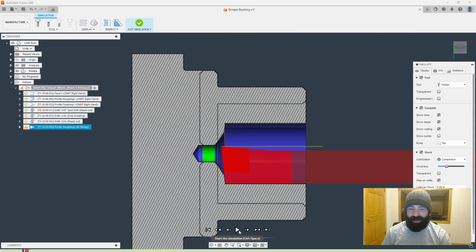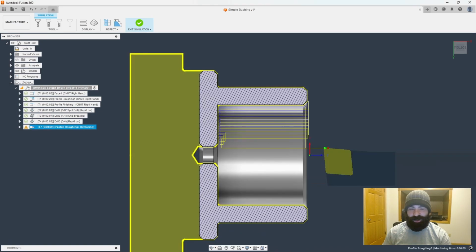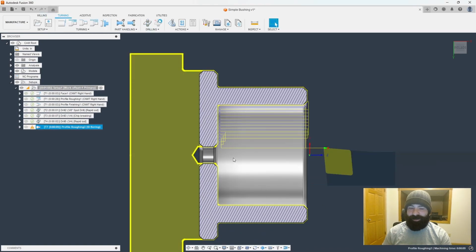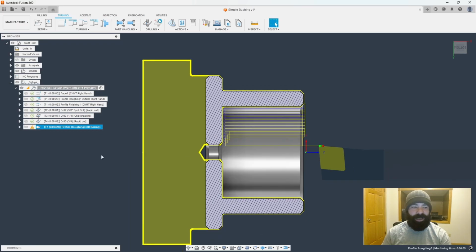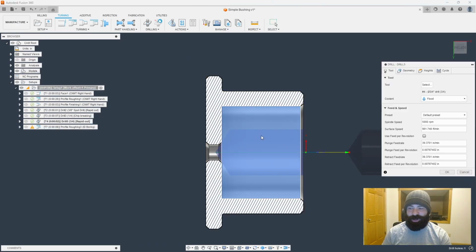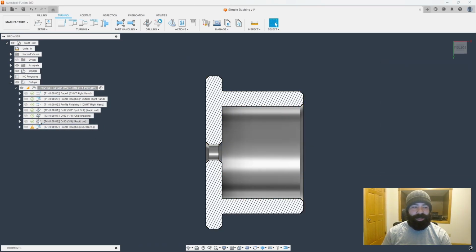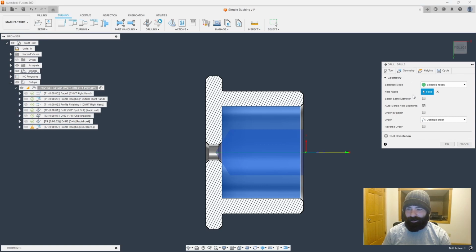So based on making a lot of different changes inside of our profile, we are still crashing the backside of that tool because of the angle of the drill. We are seeing this in a real-time, real scenario situation. Again, this is very handy depending on what you guys are doing or how you're trying to fix these problems. What I would actually do is switch out my drill bit, or go with a drill bit that has more of a flat bottom to it.